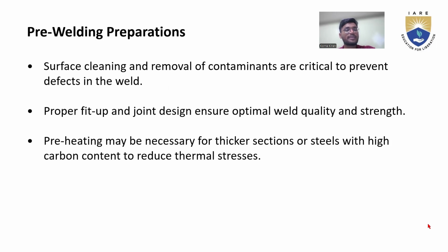Here we can see pre-welding preparation. What is pre-welding preparation? Surface cleaning and removal of contaminants are critical to prevent defects in the weld. While we are welding, we need to clean the surface for strong joining of the given material, so there is no defect on the metal. Proper fit-up and joint design ensure optimal weld quality and strength. Preheating may be necessary for thicker sections or steels with a high carbon content to reduce thermal stresses.